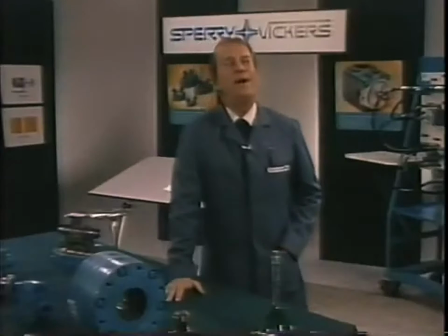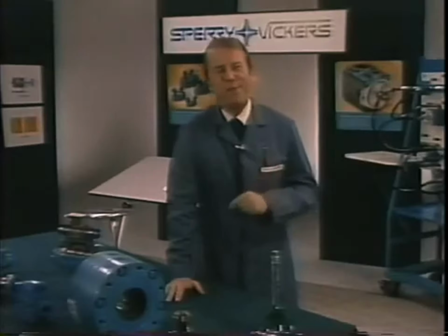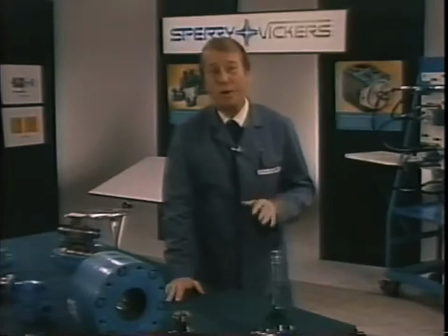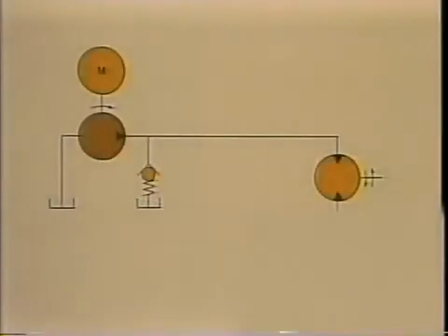Oh, you say, wait a minute. Let's put a relief valve in this line. A relief valve doesn't have to be anything more than a ball held on a seat by a spring. You just tighten up on the spring until it's harder to push the ball off its seat than it is to drive the motor with its normal load. Overloading the motor would cause the ball to lift off its seat and divert the pump flow back to the tank, permitting the pump and electric motor to run even though the hydraulic motor stalled.